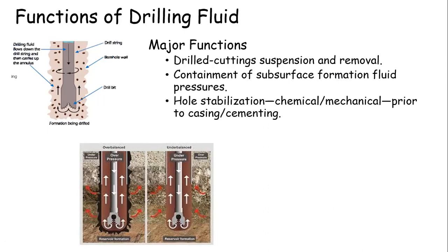Now I want you to picture the wellbore as a pressurized zone, just as when you buy a Coke bottle and you shake it, you know that the Coke in it is pressurized. Once you poke it, you notice that it is trying to force itself out. That is how the wellbore is. So you need a drilling fluid that will help you contain the outcoming wellbore pressure. That is what Foster asked about a blowout. So your drilling fluid needs to be able to control what we call a blowout.